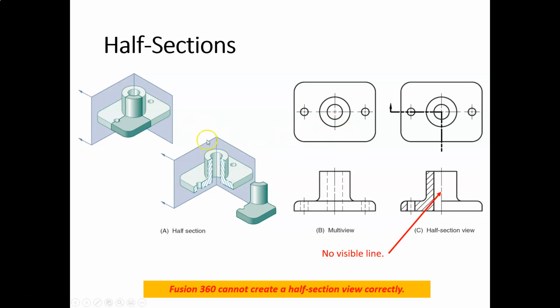It's a little bit hard to understand what we're drawing in this graphic, so let's look in this view. Here's the regular view, right? You can see clearly that we have a hole here that remains hidden. If we want to expose that hole, or expose the wall thickness on this pipe, then we could put a cutting plane line, and notice for the half section, the cutting plane line starts here and we have the arrow on that side as normal. It comes through the middle, then takes a 90-degree turn and comes out towards where the section view is going to be placed.